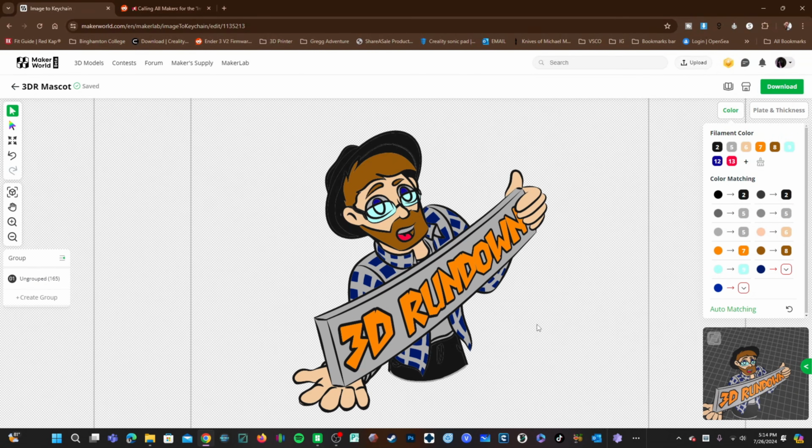Now just earlier you saw me manually select each item and reassign its color. However, you can do it all at once. You will notice that these blues are assigned to color number 10, and color number 10 is currently not active. However, if you look here on the graph, you will see the color blue assigned to no number, and this color blue assigned to no number. Looking at this color blue, matching it right here, click the pull down and assign it to number 2. Now, number 2 black has been assigned to all of that blue.